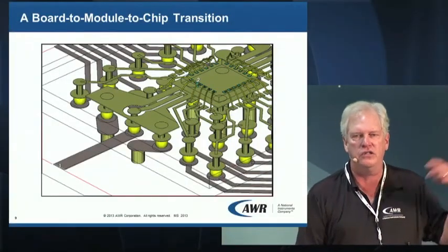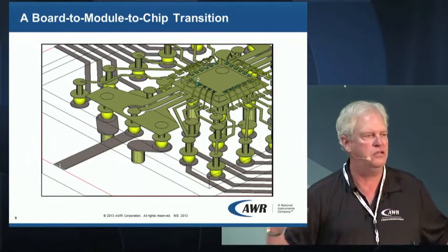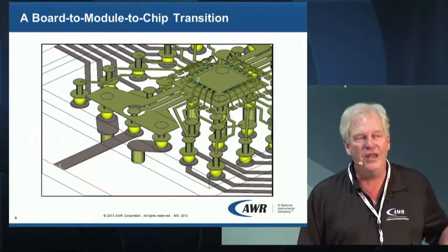Guess what? When you're doing circuit simulations on boards, it's almost always the same setup. So in our software, you draw the line over, you go, it's a port, you're done. Automatically a wave port, impedance is right, number of modes has been figured out, you're done. We can do that because you're always in those types of environments, okay? If you're on your automobile, I can't do it.